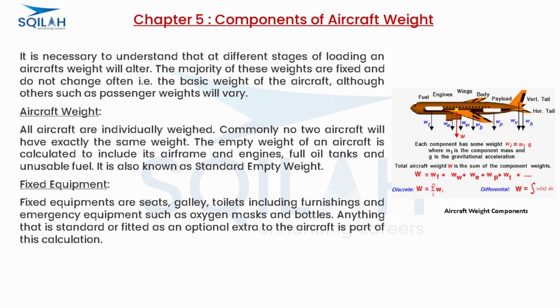Aircraft weight. All aircraft are individually weighed. Commonly, no two aircraft will have exactly the same weight. The empty weight of an aircraft is calculated to include its airframe and engines, full oil tanks, and unusable fuel. It is also known as standard empty weight.